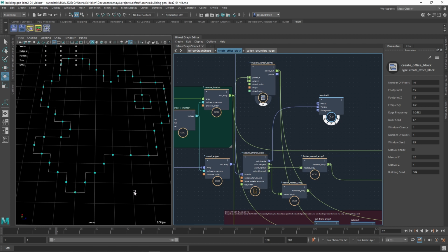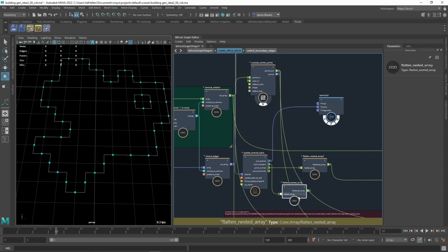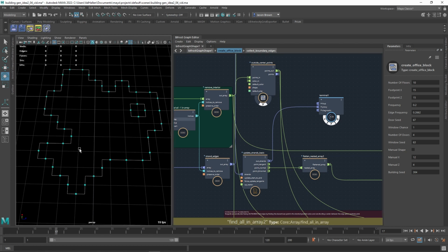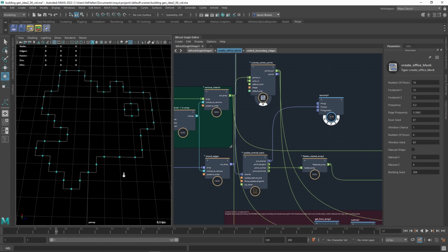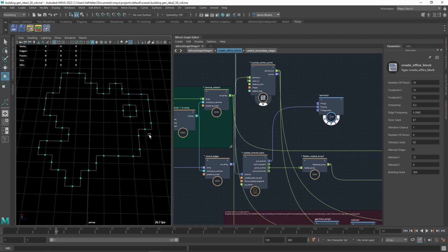So if I wanted to take this later on and make rooms in there, I could do that. It's something that I'm going to work on later, but it's a really good idea. Don't need that right now. It can go away. Now we're getting closer. At this point, we could put walls on this. So these are the points. We could instance walls on these right now, and it would work, but every single wall would be pointed the same way.